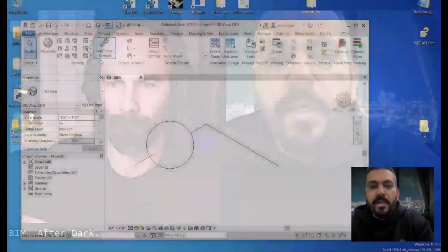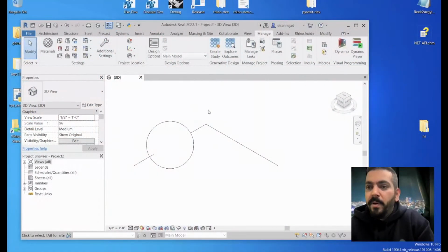And it's going to be the same in Dynamo, in your own plugins that you write, or in Grasshopper or anything else. For example, we have project parameters in Revit that we manage through the project parameters. There's nothing in the API that lets you create project parameters. That's a limitation. Grasshopper is going to have the same thing. Dynamo is going to have the same thing, all that kind of stuff, right? Right. So that's the primary limitation.